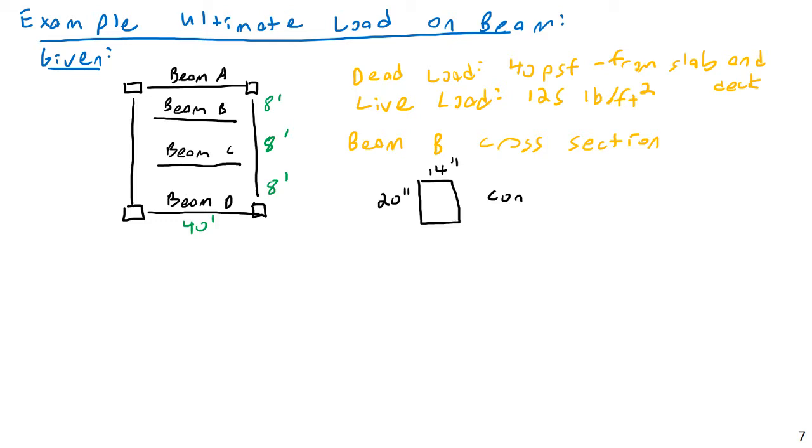And so, yes, we add other things to that. We add carbon, and then we add a whole bunch of other trace elements like molybdenum and chromium and copper and everything else. But really, all of those are just small spices thrown into the iron that will give us various other properties, including higher strength. But at the end of the day, 96, 97% of all that stuff is still iron, and iron has a certain density. So even though by adding different elements and changing the heat treatment and things like that, you can get radically different strengths of steel, at the end of the day, the density is all going to be about the same, about 490 pounds per cubic foot.